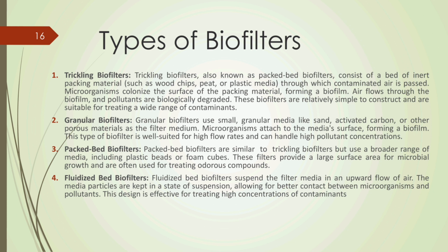Second is granule biofilter. Granule biofilters use small granule media like sand, activated carbon or other porous material as the filter media. Microorganisms attach to the media surface forming a biofilm. This type of biofilter is well suited for high flow rate and can handle high pollutant concentration.